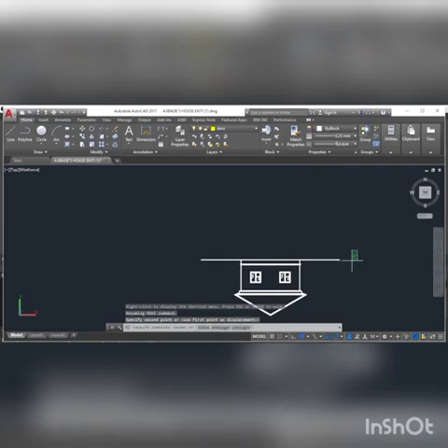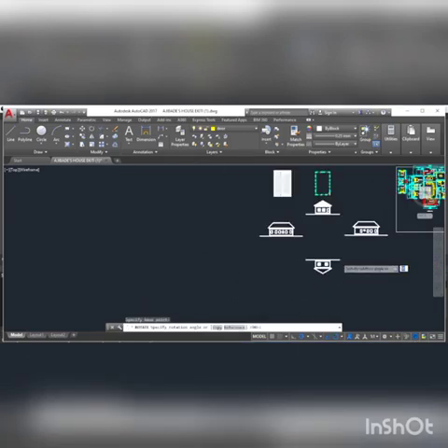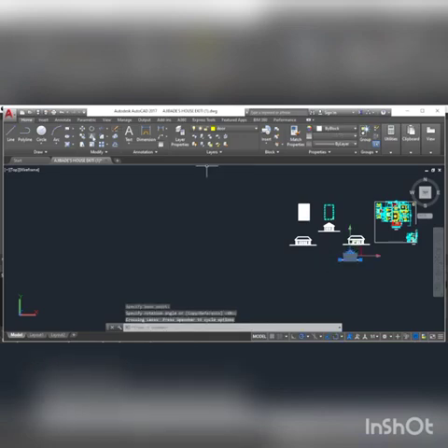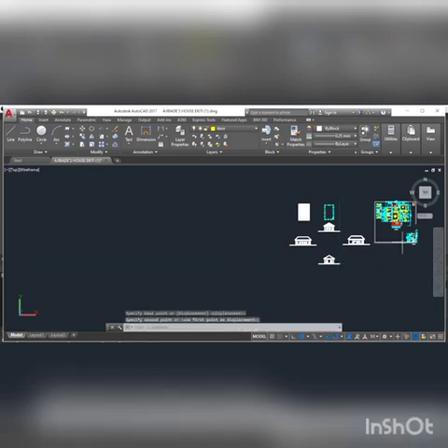So after doing that, I highlight that again, then I'll use my rotate tool. So I'll just rotate this, pick it from this point here, rotate this like this. So once I'm done, I highlight and position properly using my move tool. I'll take it from here, then I'll put it here. So I'm done. So this is my front view, my right view, my left view, and my rear view.